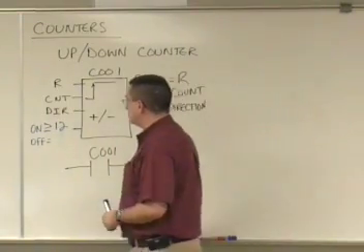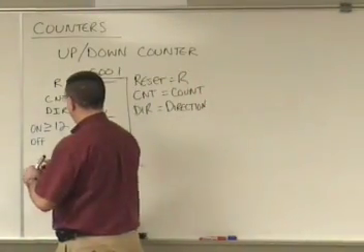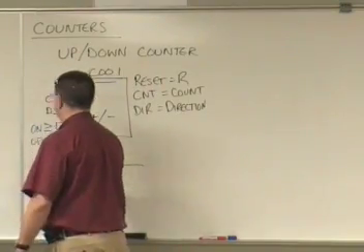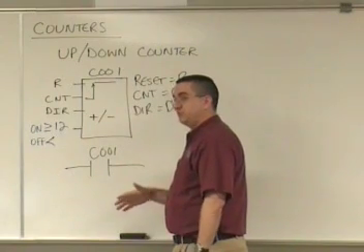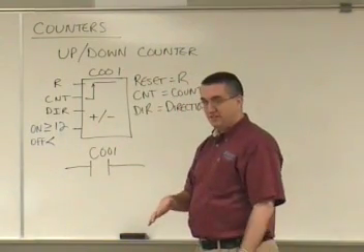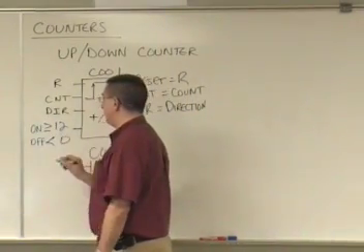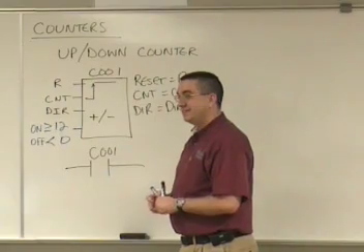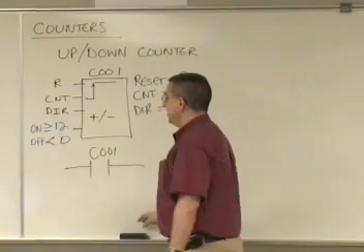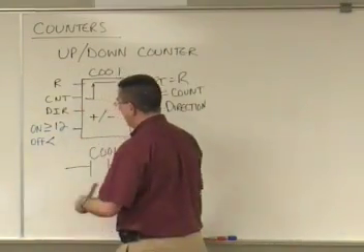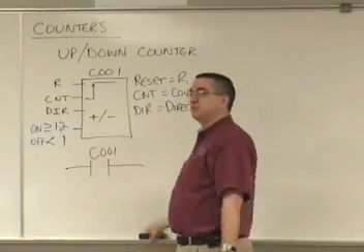The one thing that's a little bit strange about the logic is the off threshold. The off threshold is only less than that number, okay? It will not turn off at the off threshold number. It'll turn off at one less than that number. So you get into a little bit of trouble if you put the number 0 in there. Why? It wouldn't work because I'd have to get to a negative number to be less than that. So typically, I like to use 1 in there as my off threshold. So anytime I'm at 0, it will turn off.